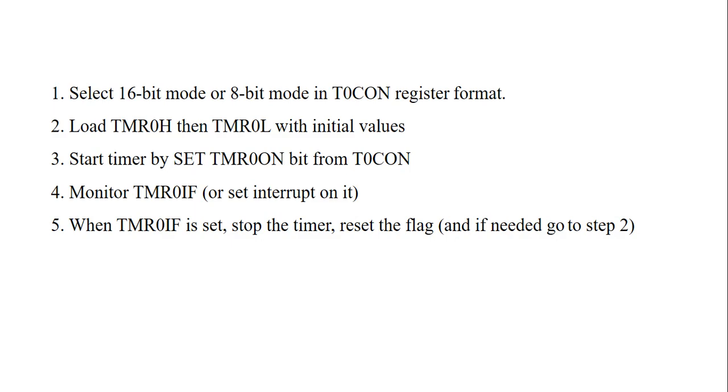Already I said that these SFRs are bit addressable, so a single bit we can set or clear. If you want to start or enable the timer, we can set that particular Timer 0 ON bit. Then monitor TMR0IF, which is a bit from INTCON. This bit tells whether the timer has overflowed or not.